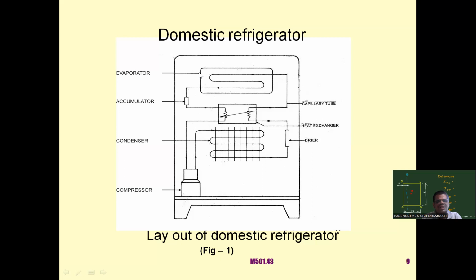If you see, your pressure box is nothing but the evaporator, in which the evaporator coil is placed, and it is located at the top, and the entire fridge space is cooled by the cooling produced in the evaporator. Okay, see, and here the capillary tube is placed.